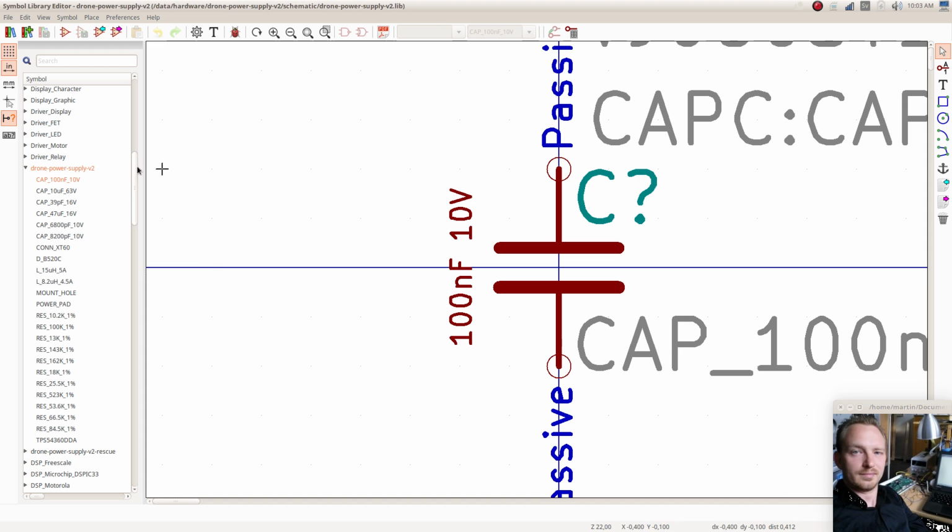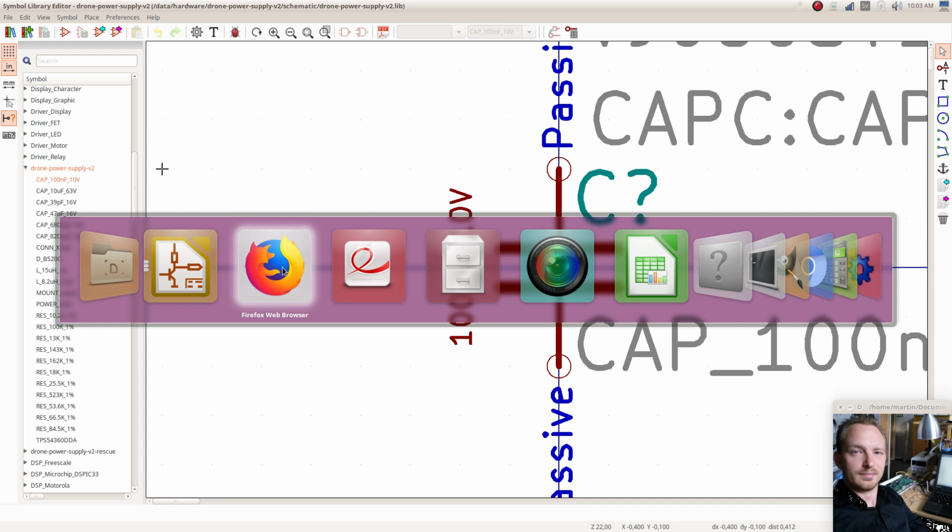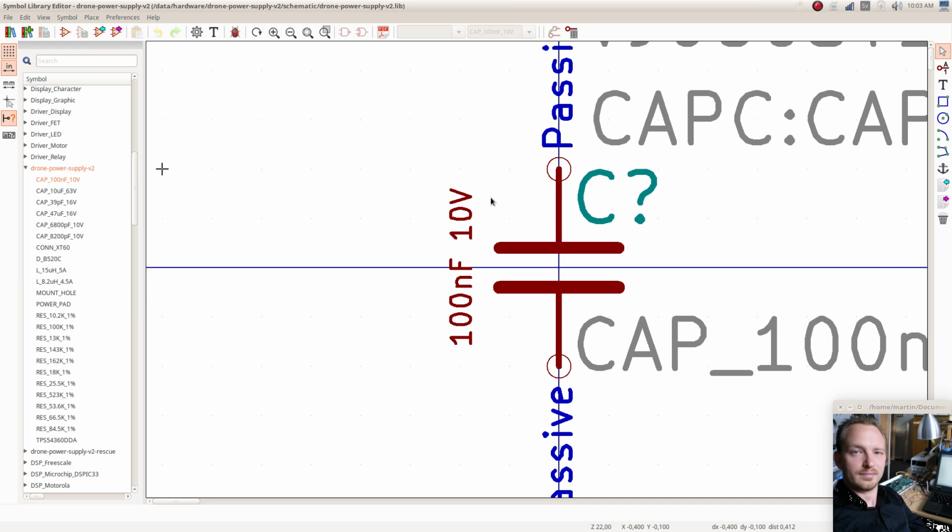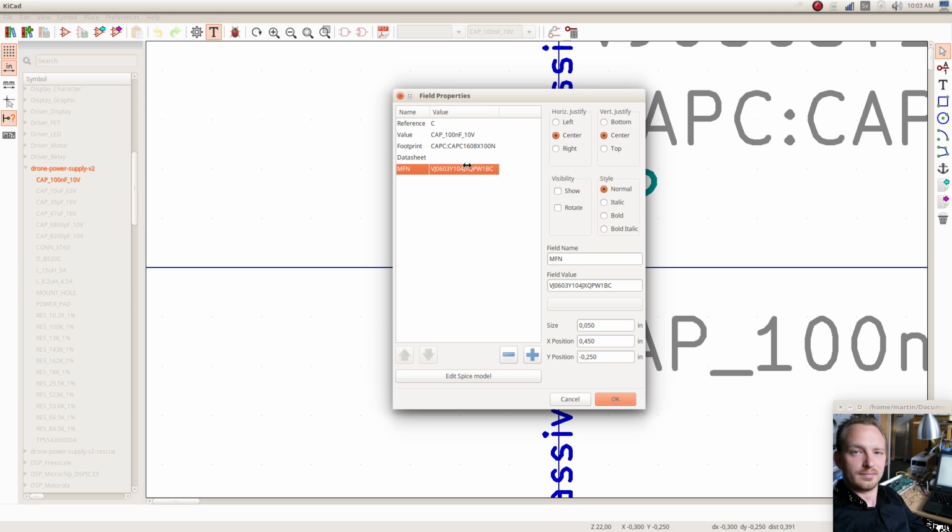So let's say we create a new capacitor, and we go to Mouser and pick any capacitor, and we know that it has a certain width, a certain length and a certain height. The proper way, which I see as the simplest way, to create a footprint for this capacitor is from this simple text string that represents the chip capacitor footprint.